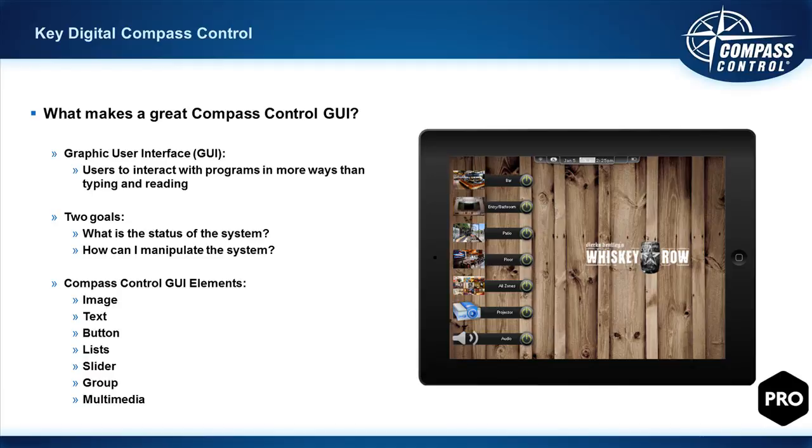And there are many control systems that still do not support sliders and other advanced logical elements, because if you think about it, those control systems have buttons like 0%, 25%, 50, 75, 100%. And the button has just one event on it, right? Set the volume level, for example, to 25%. A slider needs to be dynamic. It has one event on it: set the volume level to X. And X is the value of what the slider stops at as you drag your finger.